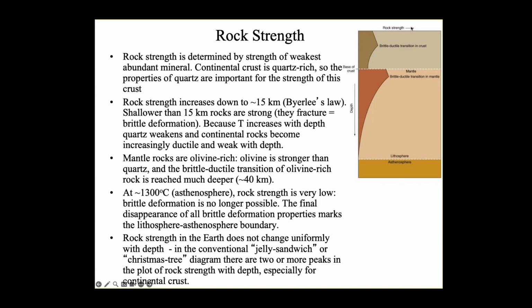Hey, I was thinking being a 7 on Mohs hardness, maybe it's just because of its silica content. Mohs hardness is a good example of brittle strength, not ductile strength. You're doing Mohs hardness tests at atmospheric temperature, nowhere near the temperature of melting of quartz. Clint, does this have to do with quartz having the lowest melting temperature, so the homologous temperature would be lowest? Yes, exactly. Good point.